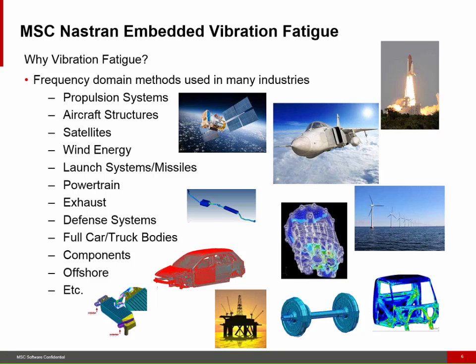So in the frequency domain, you often see benefits over time domain methods, and that's the intuitive way to find the dominating frequencies and study the eigenmodes that act at those frequencies in order to find the root cause of your structural dynamics problem. So that is also valid when you go to the fatigue side. If you do fatigue in the frequency domain, you have a more intuitive way to find your root cause.